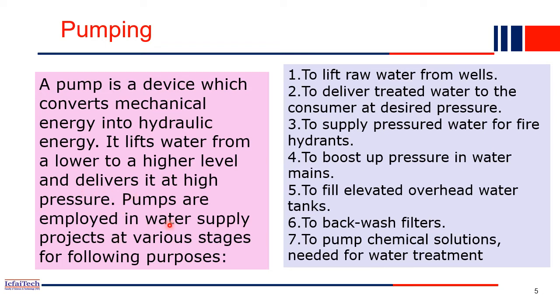So pumps are employed in water supply projects at various stages, and these are the below. Pumping is very important in the entire water supply system. Pumps are required even for the collection of raw water. In the last slide I explained the intake structure, right? Intake structure means where we are collecting the water from the source. So there also we need pumping. Pumping is required to lift the raw water from the well or from the river or from any source, right? That is where we need a pump.